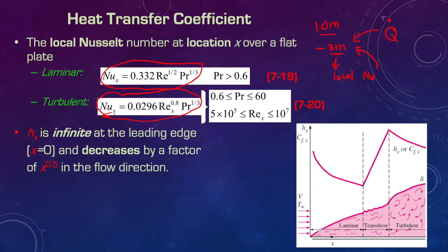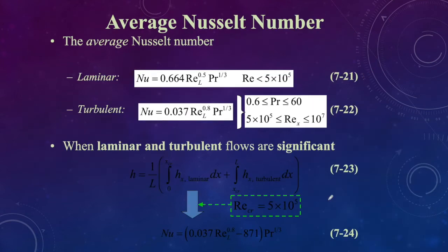In this figure, it shows that the heat transfer coefficient has different values when the x coordinate increases, and the heat transfer coefficient reaches its maximum when it falls into the turbulent flow regime. In laminar flow it will decrease, because heat transfer under laminar flow is not as effective as in turbulent flow.